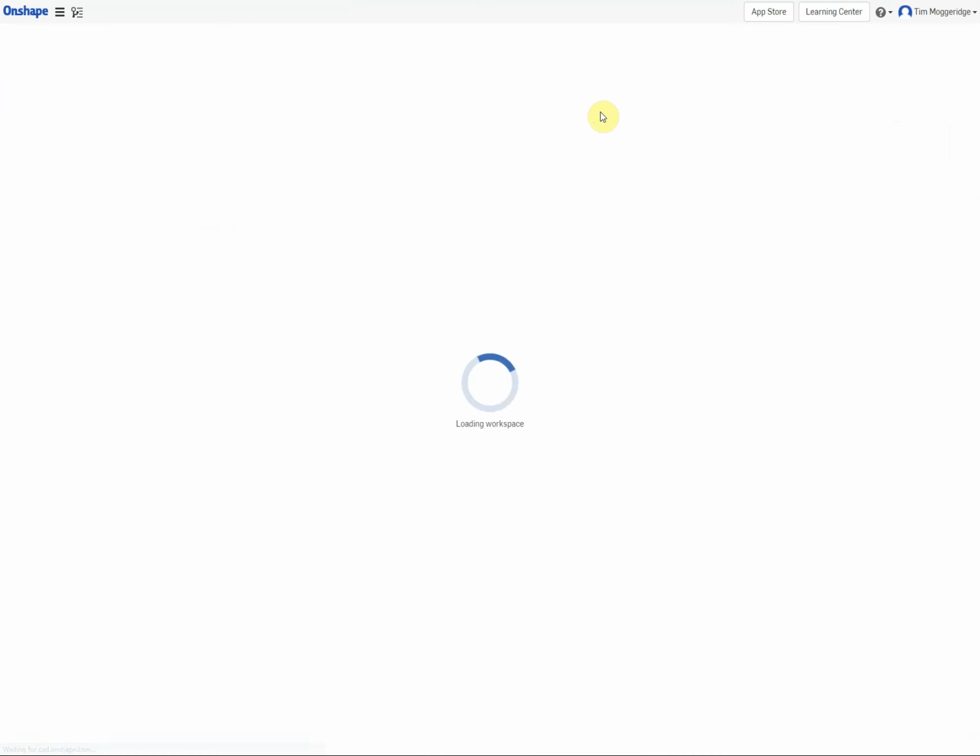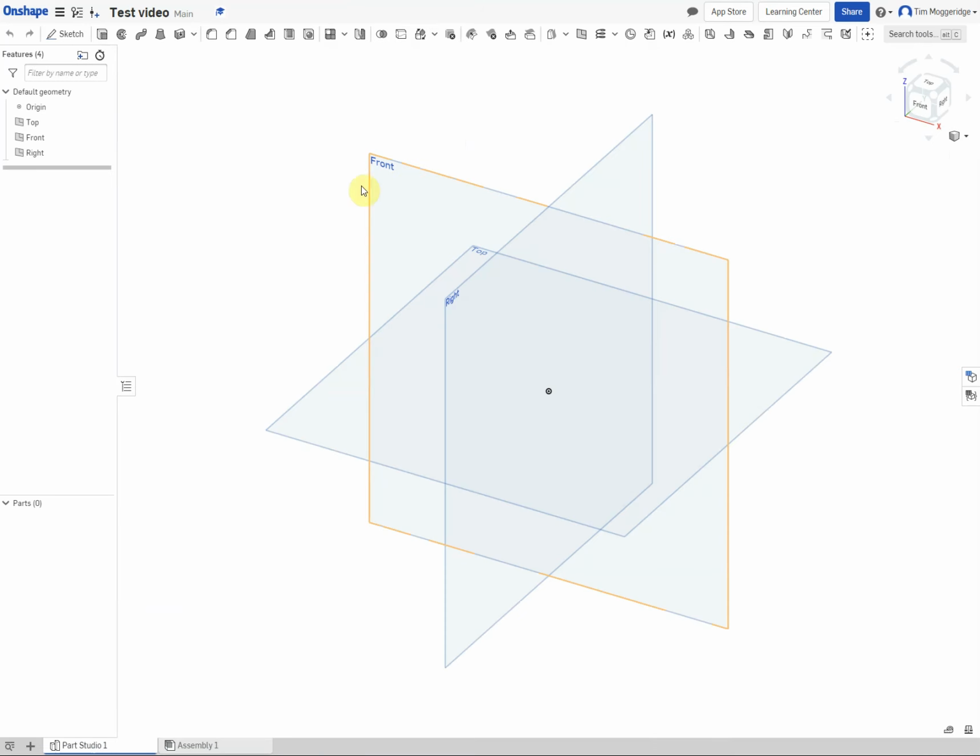And then that will take me through to the modelling area, the modelling screen. So on this side, effectively what will appear here are all the different sketches and features that we create. So this is our design tree. You can already see that we've got an origin and 3 work planes. If you look over here, you can see the 3 work planes that are labeled front, top and right, and we have the origin in the middle where those 3 work planes intersect.